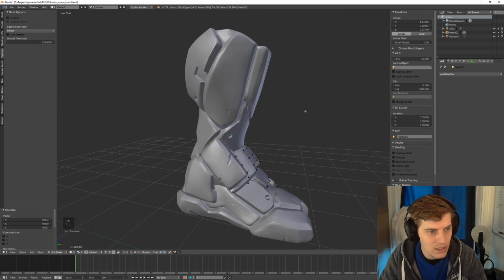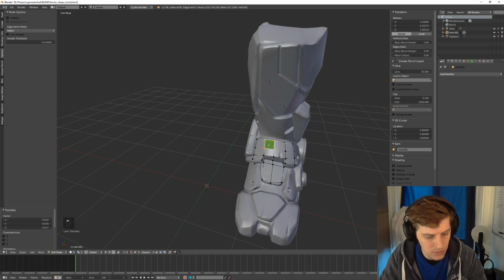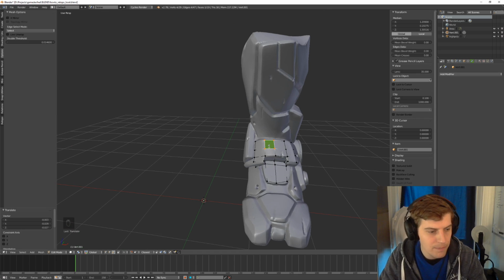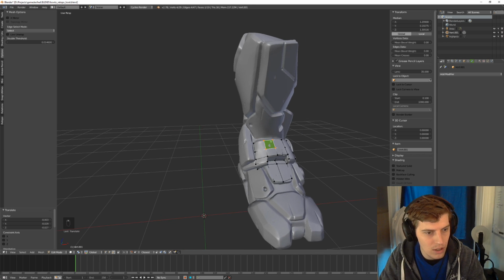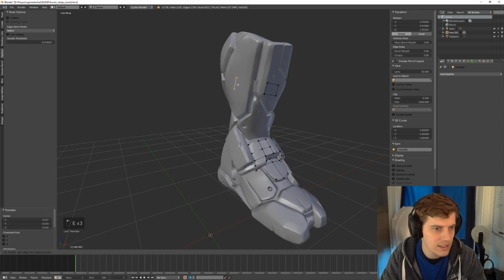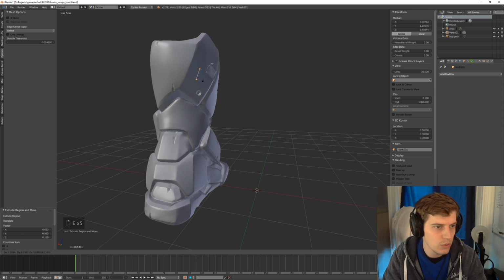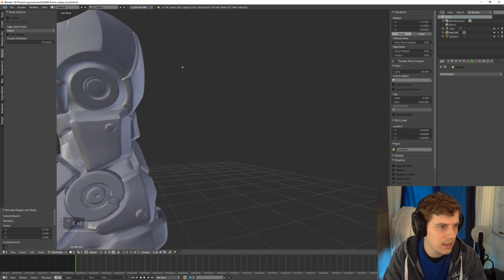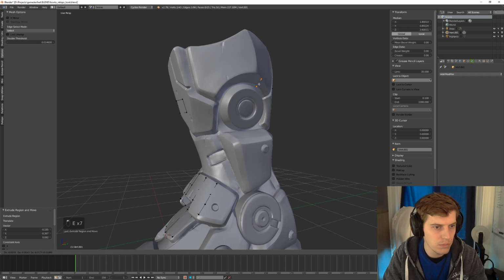So I want to illustrate another small problem. I just selected this poly, and you can select polys without going into poly edit mode by selecting two edges that are parallel to each other. Then I'll press Shift D, and I'll drag this out, and I just duplicated the poly. So let's say I'm going to loop this around like that. I'm not going to bother too much with having nice topology.